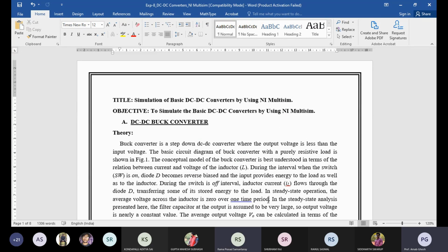Okay, and the mode gain. In this case the gain is not possible, but in isolated converters the gain is possible up to 10 times. So you can amplify up to 10 times, as well as get multiple outputs. That's the benefit of the isolated DC-DC converter. But here we are mostly focused on the non-isolated DC-DC converter.